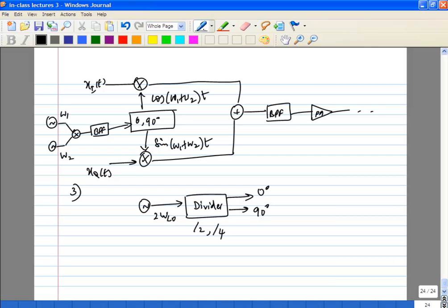Effectively what happens is, if there is any parasitic coupling, it is going to be from the PA second harmonic, and typically anyways you try to minimize the PA second harmonic. Okay, so the assumption is it will couple less, it will pull less, that is the hope. Obviously, as you go to higher harmonics, if you use divide by 4, it will pull even less. Okay?